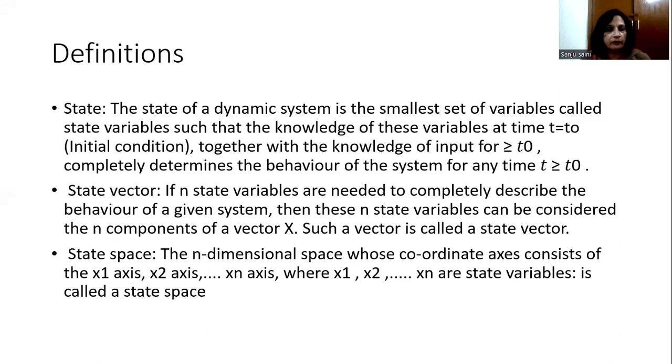So I can take two state variables, position and velocity. Anyone else can use other state variables, but the condition is that the state should be represented by a minimal set of variables, because as the number of variables increases, the total calculation time will also increase. The second thing is that the chosen set of state variables should completely describe the state of the system at any time.